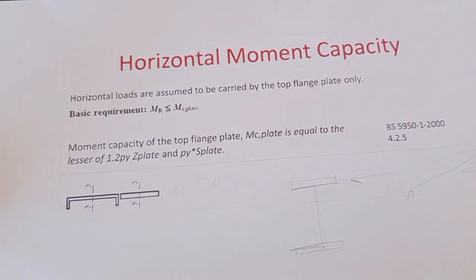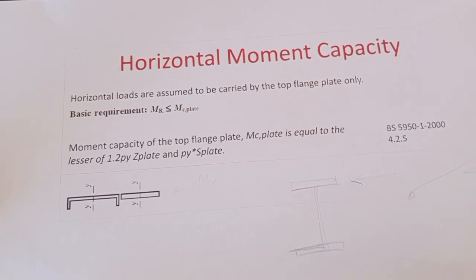Now, if it is safe, it's okay. If it's not, we need to have a higher section for the whole area, or we need to strengthen the top flange.